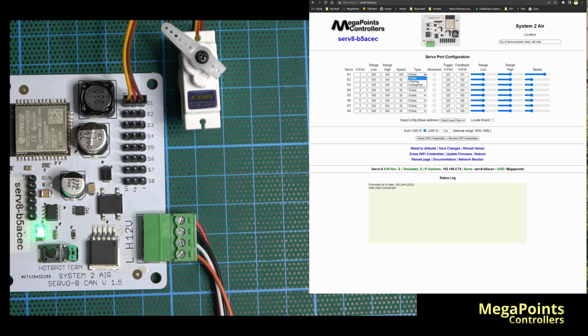We also have a semaphore signal. So if I just select the semaphore program, now what happens is I'll get this crazy bounce and a pull off, crazy bounce and a pull off. And that's because generally semaphores work over a 45-degree range, not 90. So I could reduce the range of motion here a little bit and maybe slow it down. Let's see how that looks. And by the time you've fitted it to your semaphore signal through the piano wire and various other bell cranks and things that you might go through, you can adjust it, try it until it looks pleasing for you.